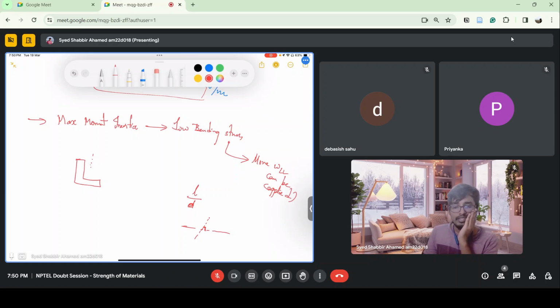There we'll take the shear effect also. So in this week, whatever we have discussed is simply pure bending. Pure bending means we are assuming that there is only bending moment acting, and for that we have discussed various things, and we can also see there is also effect of shear. So effect of shear can be neglected for thin beams, for which the depth is less. But